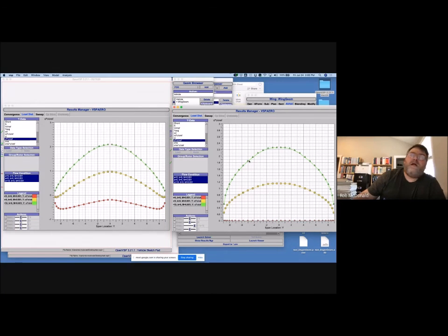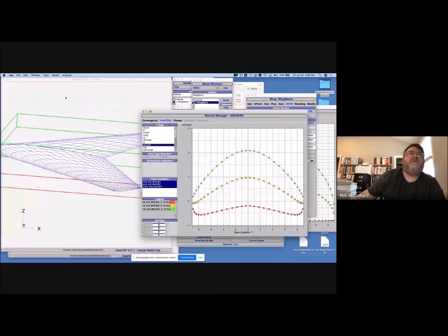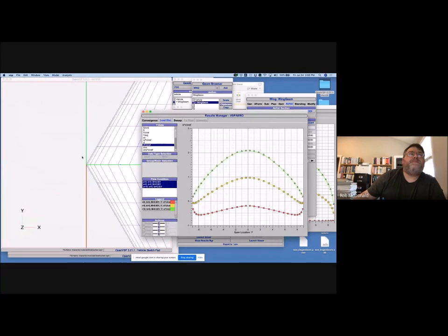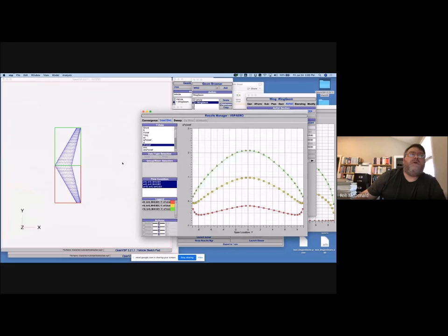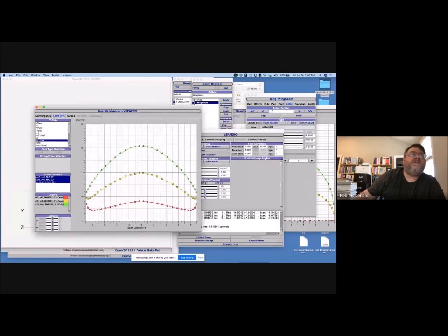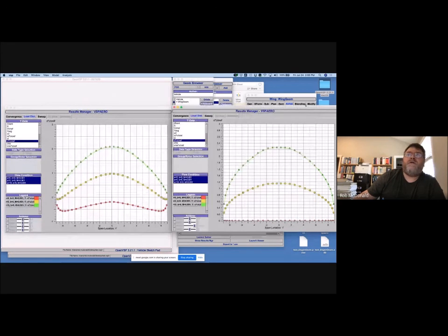Okay. And what'll really blow your mind is the additional lift distribution, right? The delta between these curves is only a function of plan form, i.e., what does the wing look like when you look at it from the top? The additional lift distribution is only a function of plan form, not camber, not twist, not airfoil. And these two wings, they have the same plan form.